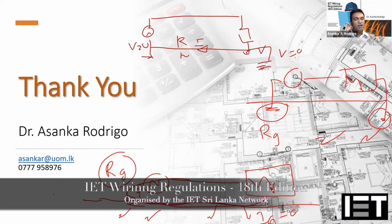Even the Singaporean standard uses BS 7671, but they have amended several things to suit their environmental conditions. For example, even though TN-C is defined in the IET Wiring Regulations, they have banned TN-C installations in Singapore. Likewise, they have adapted things locally, so it is up to the local standards institute to take that forward. At the moment we are following it as it is. As far as I know, there was a discussion a long time back to have our own standard, but the idea of most senior engineers and senior professors was to keep it as it is.